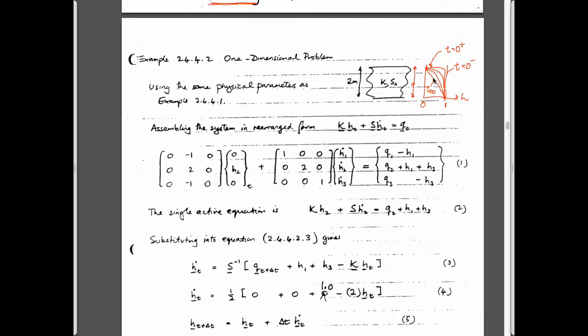But we also know that because we only have two elements here, we're not going to be able to capture all of this nonlinearity, this parabolic, quadratically curved shape. It'll just be two segments of a linear distribution because of the nature of the elements we use. Okay. So, what do we remember?